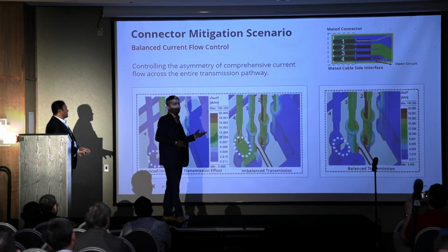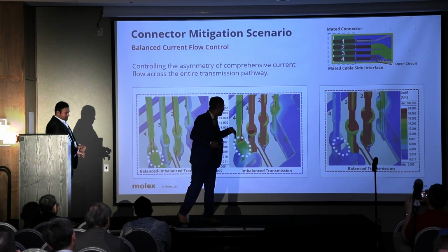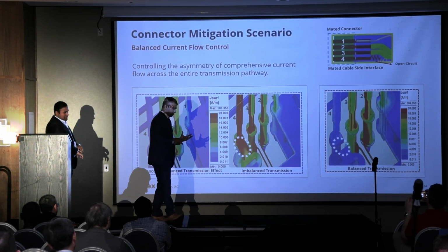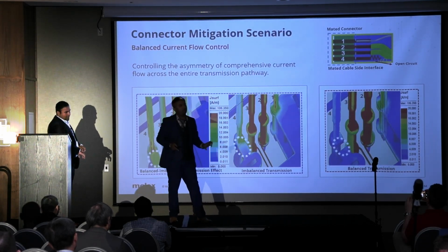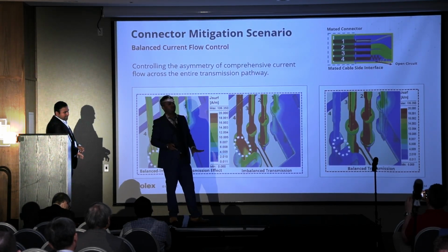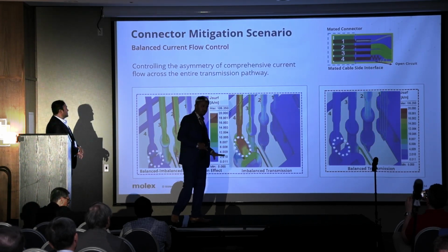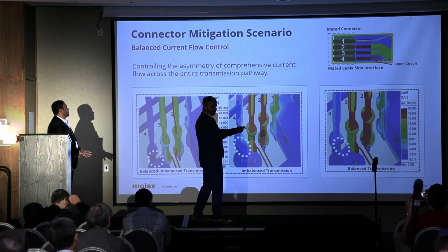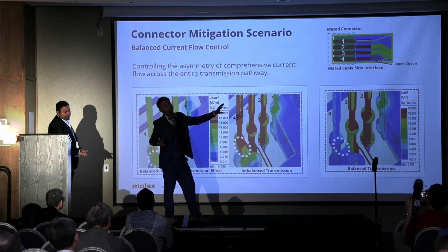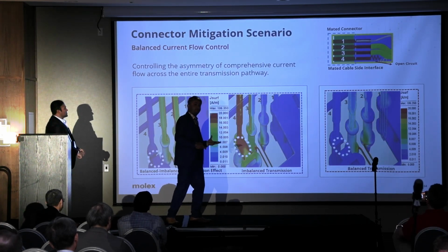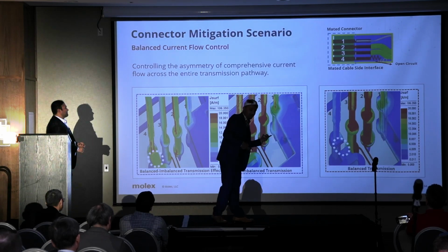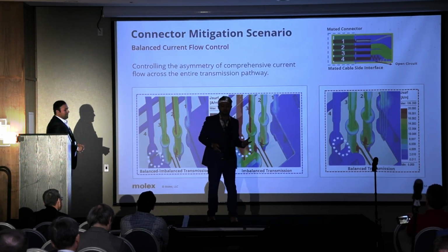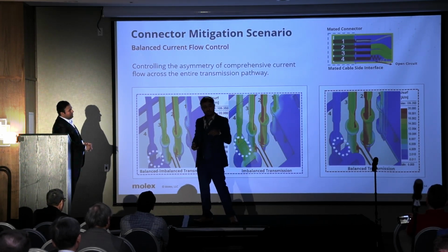It might create an extra emission, right? So in that kind of situation, one thing is, since it is open on the far end, I can keep it open on the PCB side, so that this noise is not injected into the system, it is not going to the ground. So the condition of low impedance and high impedance is not met. So this is one technique, one idea to overcome this kind of scenario. And this kind of scenario definitely acts as an unintentional radiator.